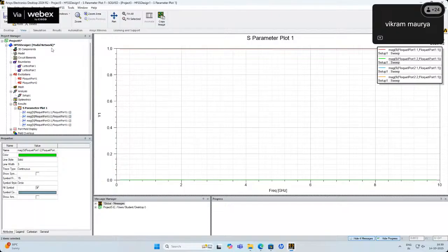How to plot permittivity and permeability in HFSS? You can't directly plot the permittivity and permeability. So the better thing is to first observe the S parameters, and then by using the permittivity and permeability formulas, you can calculate their values from the S parameters.